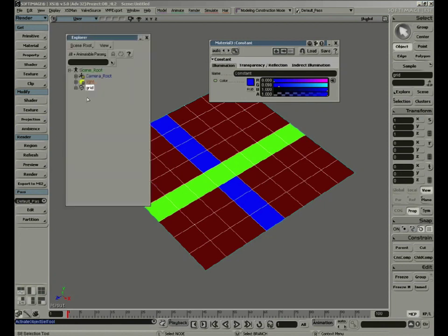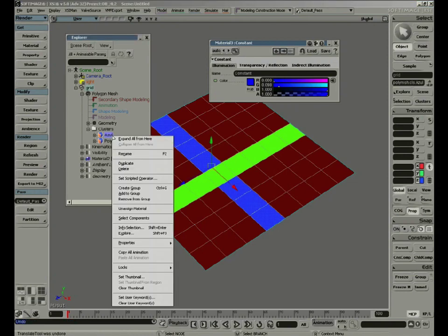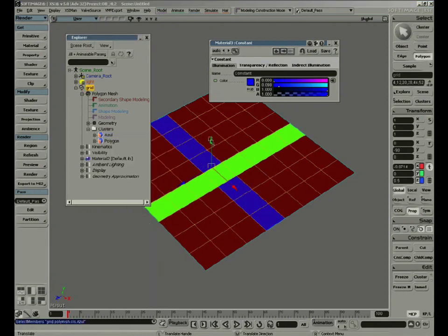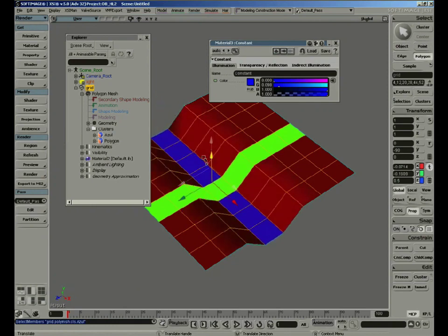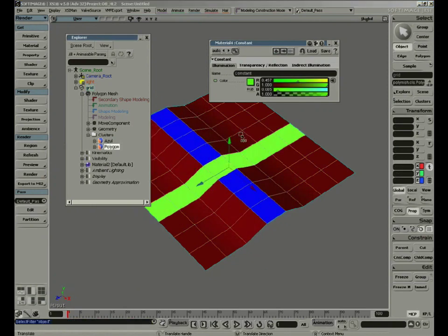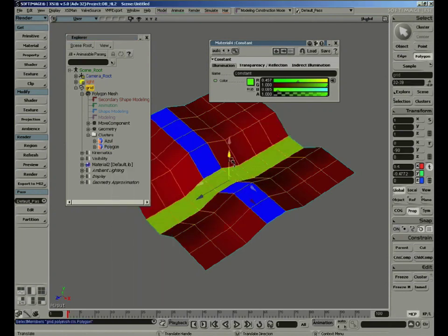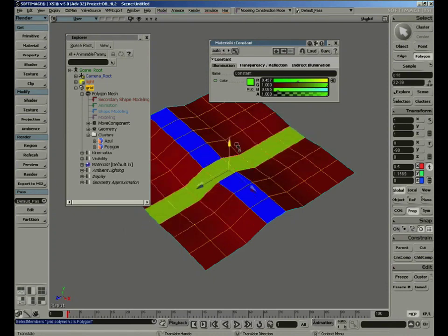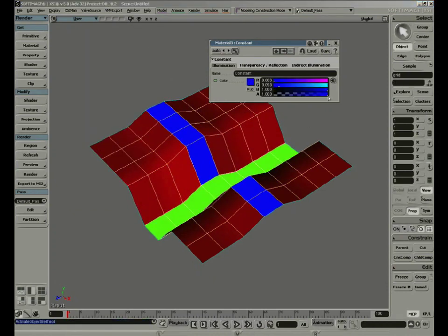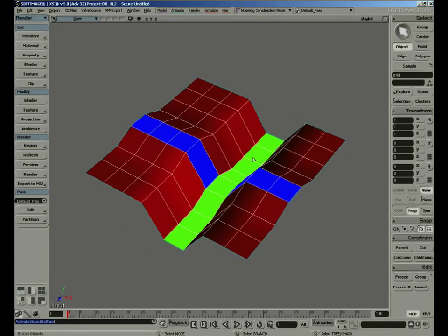If you explore it, you can see we have the original cluster. Select some components, move them around, and the color is applied to the second cluster. Select the components and move them around. In other words, the same polygon can exist in multiple clusters, but each polygon can only have one material applied to it. This way we can start adding materials to different parts of our model.